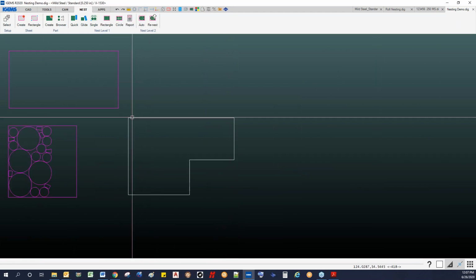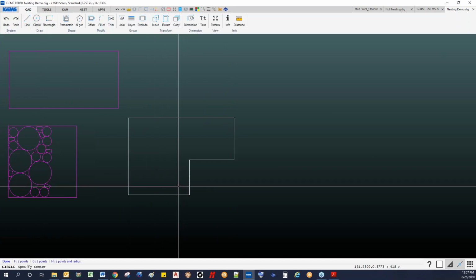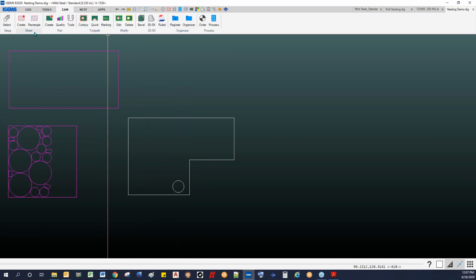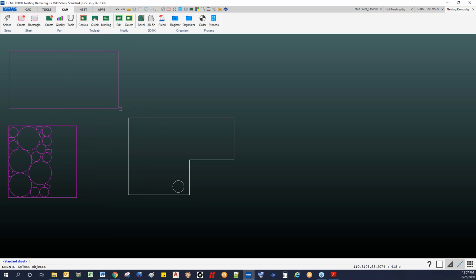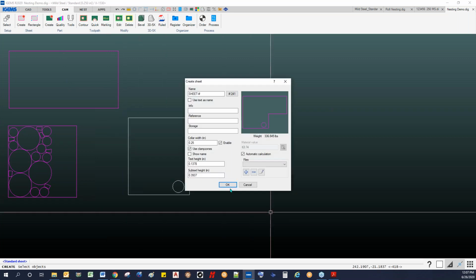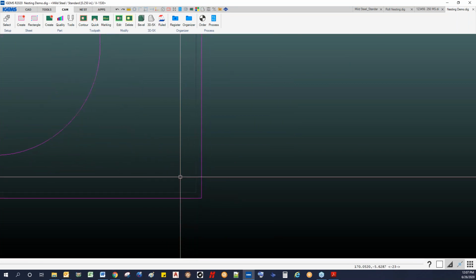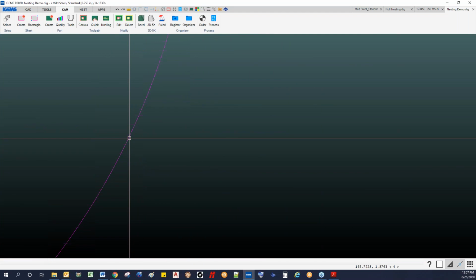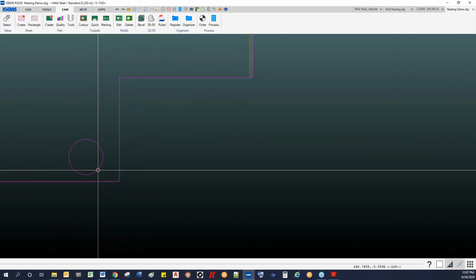One other thing you can also do is draw in other geometries. So if you've cut something out of here already, you can draw that in. Just note that when you create the sheet out of something like this, it will put that 1/4 inch collar width around the outside, but there is no collar width around this portion here. So if you're going to draw something like I've done here, you just want to make it a little bit bigger so that it doesn't nest parts too close to that void in the sheet.